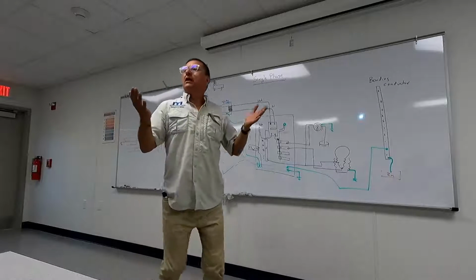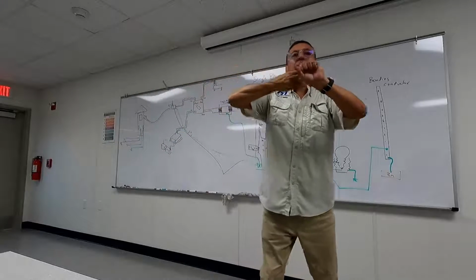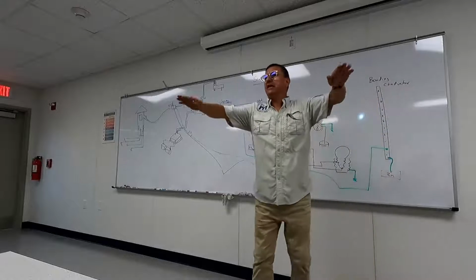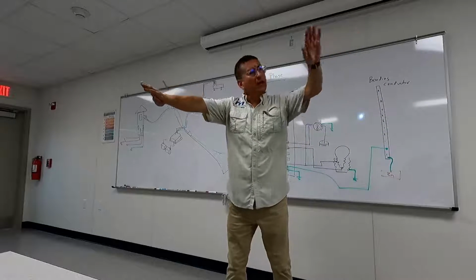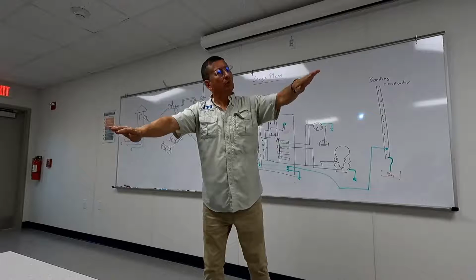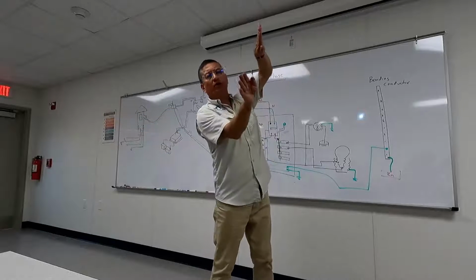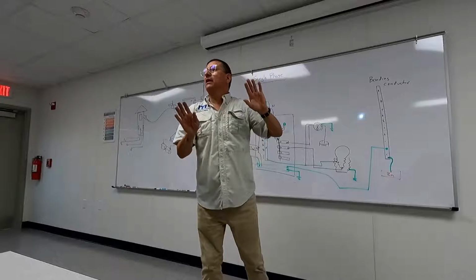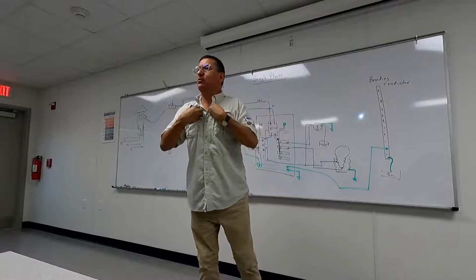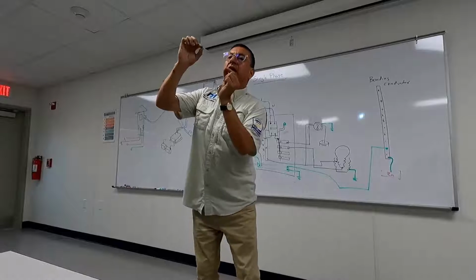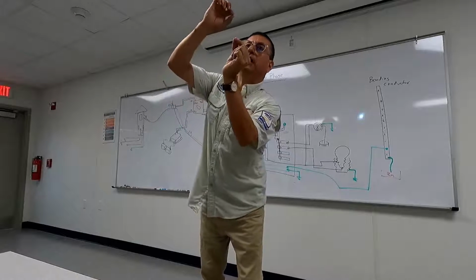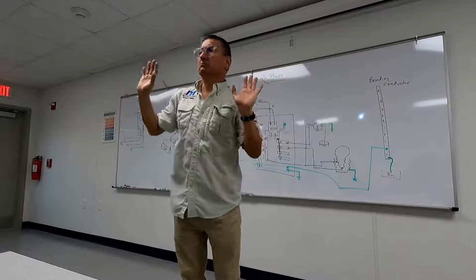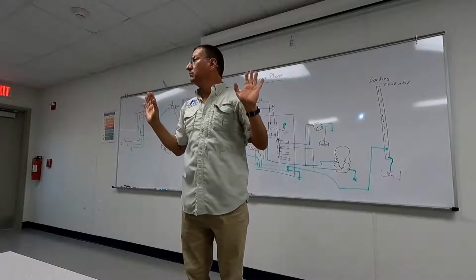I said neutral and ground should be connected together only at the source of the power. After that, they are separated. Neutral bus bar here, ground bus bar here; the bars are close but not connected. In normal condition, if my boat is properly wired and I read voltage between the ground bus bar and the neutral bus bar, how much is the voltage? Zero.